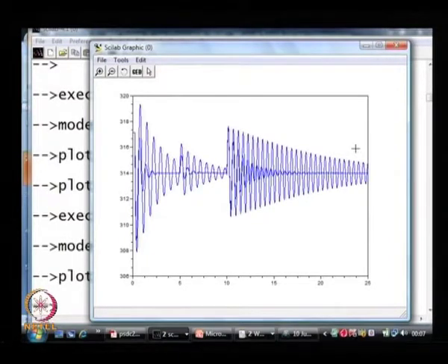This is not very surprising. In fact, one may say that the damper winding derives its name in some sense from the damping effect that it has. So, if we reduce the amount of damping by removing one damper, it is not surprising that we get this larger time for decay of the transient. Okay. So, this is something which is not at all surprising.